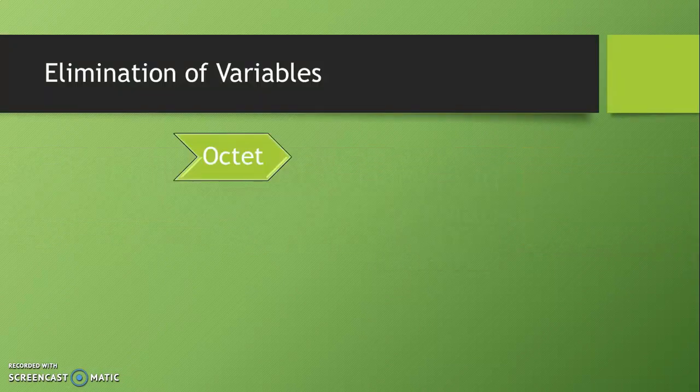We need to select a group after representation of minterms in the K-map in the appropriate cell. Then the second step is grouping. We have to make a group. In the previous lecture, we have seen that the group must be as large as possible. So priority wise, if an octet is possible, then first we select the octet. If not, then we go for a quad. If not, then we go for a pair. And if a pair is not possible, even for certain isolated ones, then we go for a single group.